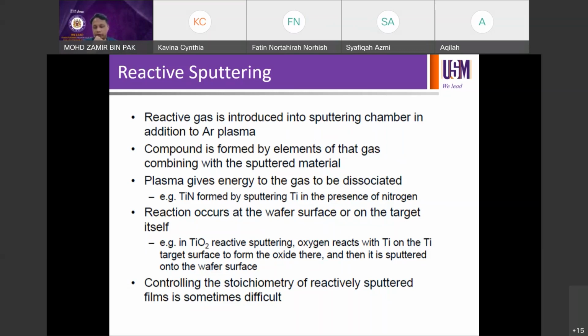deposit silicon nitride, then the typical way of doing the sputtering is by having a silicon nitride target. Okay, SiNx target material, and then you sputter silicon nitride from the target in order to get a silicon nitride thin film on your silicon, for example, or on glass or plastic or some other substrates. So that is the typical or standard sputtering that we're talking about.